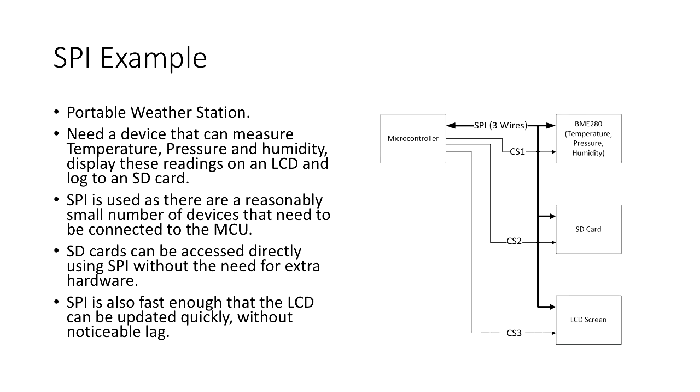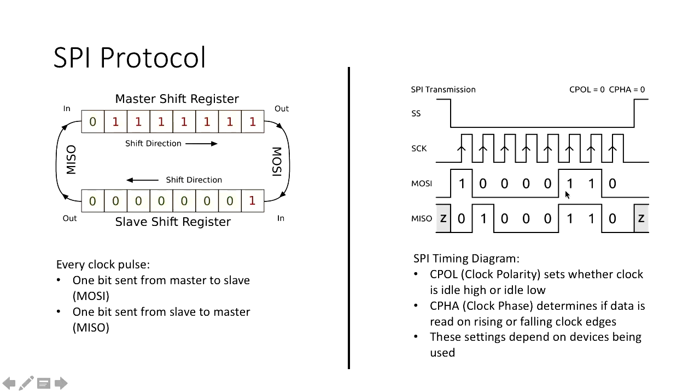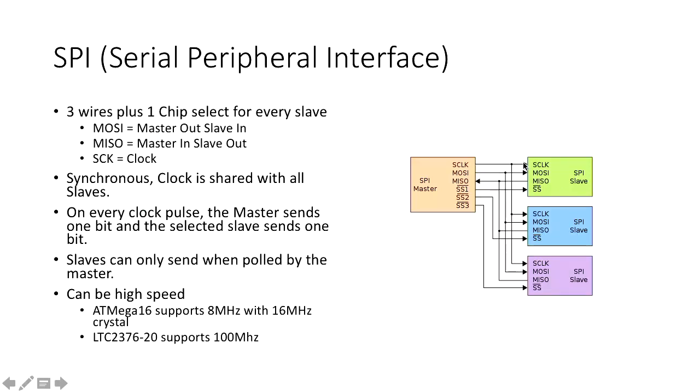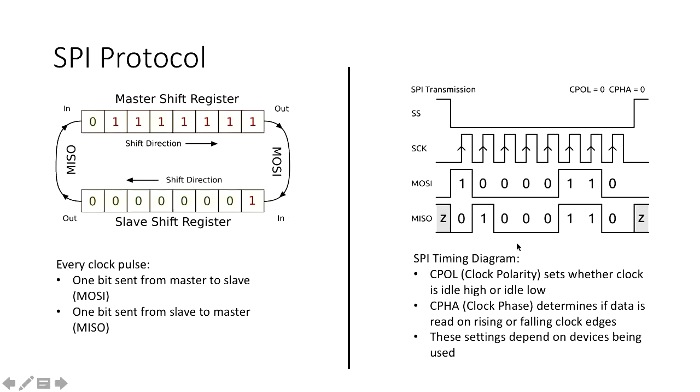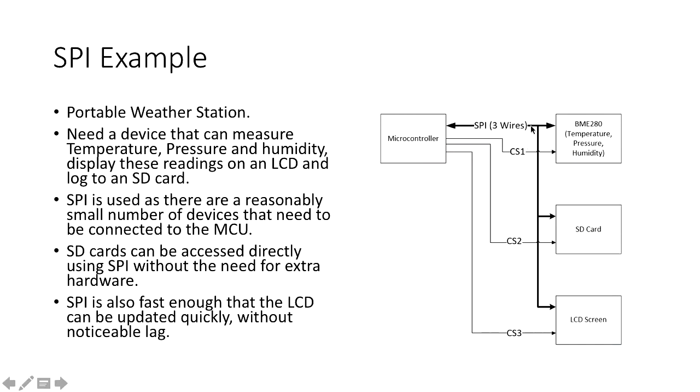Then you can use SPI. Because you got a microcontroller, and with SPI here you already got 3 wires. I have drawn only a thick wire, which means here there are already 3 wires. Then these are the control ones. You will be connecting like this. The microcontroller is your master, and these are the slaves. These 3 lines are going here, 3 lines are going here, 3 lines are going here. I have shown the 3 lines as a thick line, and then this is a select one. Which one should be selected?